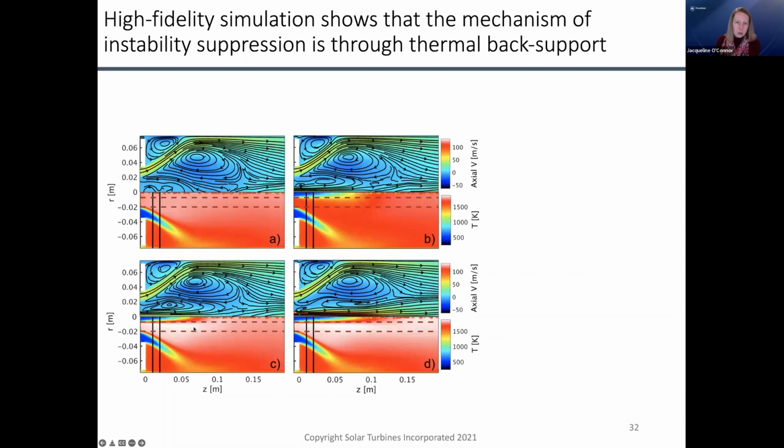The other thing that's helping you out is the fact that there's a big recirculation zone here, right? So it's not just the diffusion of heat and species laterally, but anything you generate along the pilot's going to get sucked back into the base of the flame here. In this paper, we also looked at recirculation zone strength at different locations. I don't have it in the slides, but if you look at the paper, we look at the fluid mechanics of this as well, and talk about the transport of this heat back to the flame stabilization location.